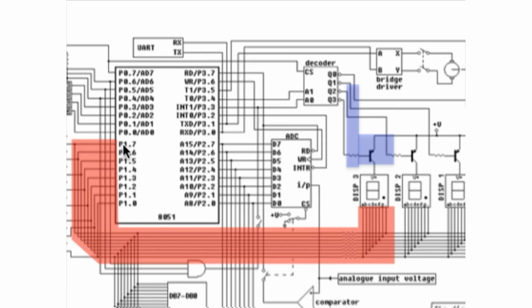So in order for light to turn on, you have to have a voltage difference, right? One part has to be ground, one part has to be supply. Because it already has the supply power part, the processor's role is different. It's opposite. It's to provide ground or not ground, right? So if you program a 0, that establishes a ground path, and that's what creates the voltage difference, and that's what turns on the light.